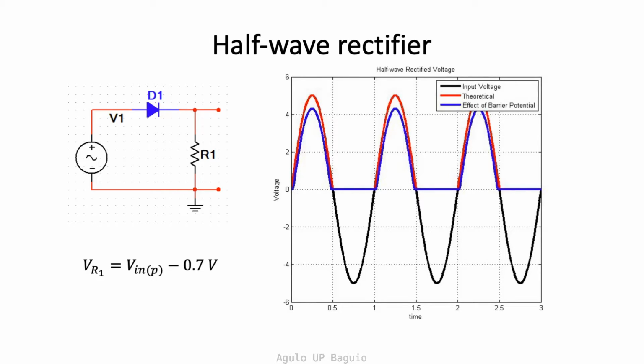If we take an oscilloscope and measure the voltage across the input voltage, we will get the black curve. The black curve is not seen in the positive portion of the voltage, or the forward bias portion, since it is superimposed by the red curve. With an ideal diode, the turn-on voltage is at 0 volts. This means that as soon as the input voltage reaches 0 volts going to the forward bias, the diode will give an output current. Without the resistor, the current would be infinite. With the resistor, the current would be V1 over R1. So the output voltage just follows the input voltage exactly.